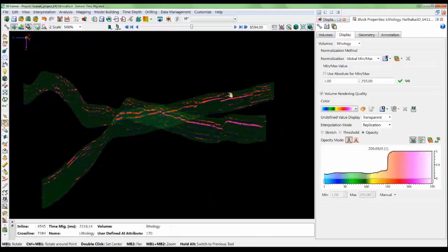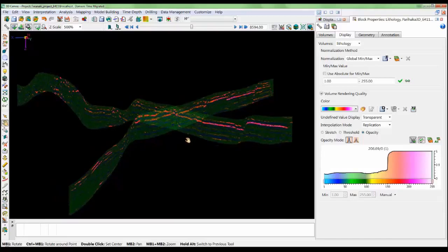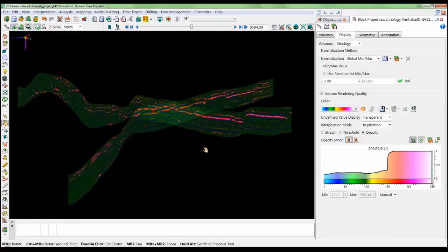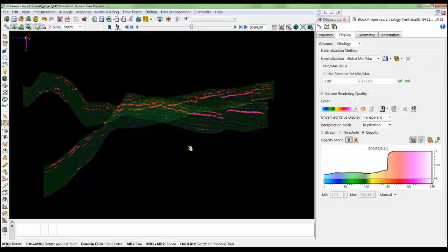Right, this is just a 2D display. So the idea would be to create a cross-plot in 3D and isolate these areas. Again, we can take this information, the full 3D volume of the cross-plots between P impedance and Poisson ratio, to our voxel-based analysis tool and detect all these bodies that would represent the pink color using our subvolume detection technique.